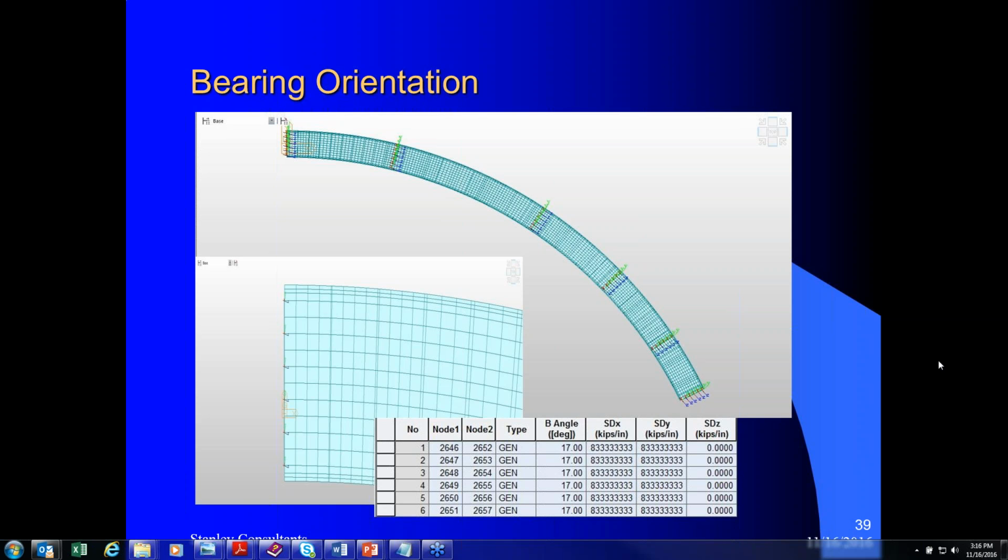Okay, next question. Were there any stability analyses done for construction erection staging? Well, here in Illinois, we do not do that. The designers usually don't do that. That's usually the responsibility of the contractor. He needs to get a structural engineer to check that and submit his calculations to the designer for review and acceptance. But that's how it's set up here.